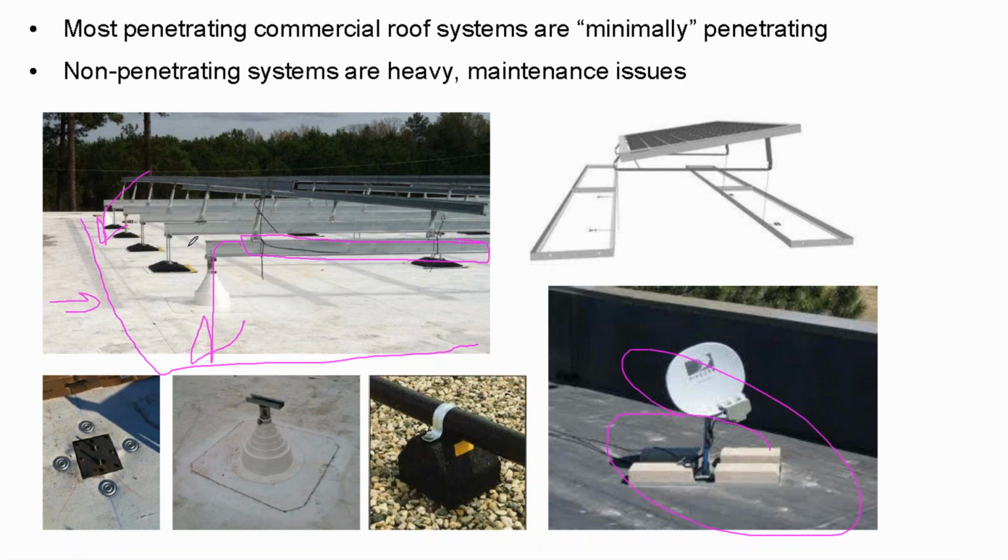And so what was happening is, in the early era of commercial solar, installers were running very long aluminum raceways with copper conductors on the hottest part of the rooftop and not putting in any expansion joints or service loops in their runs.